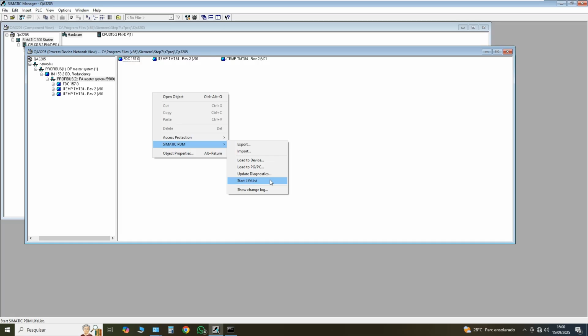So I forgot to say in the beginning of the video, but before all that, you have to install Simatic PDM. You have to have the license, and you have to install the EDD file for the device that you're gonna use.